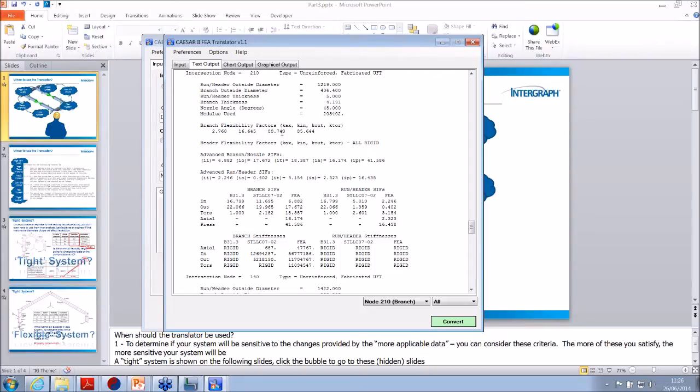The outplane flexibility factor, well, that's 80, the third one. So it's axial, in-plane, outplane, torsional. The outplane rather is 80. That would give us a lot of flexibility. Well, it's 400mm pipe, so 80 times 400 is around 32 meters worth of extra pipe. That's quite a lot of extra flexibility length.